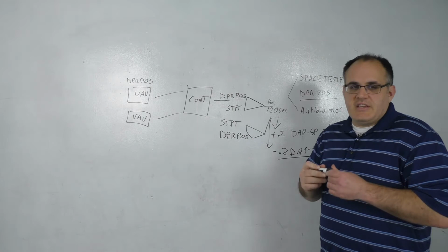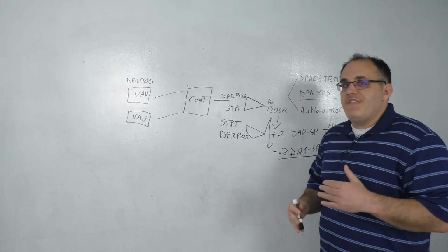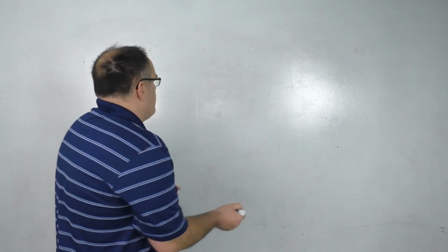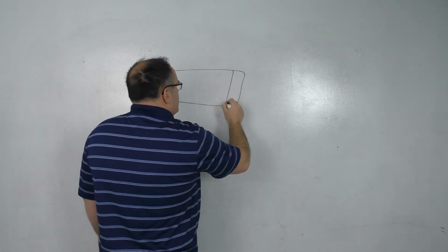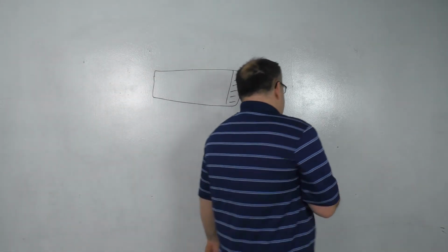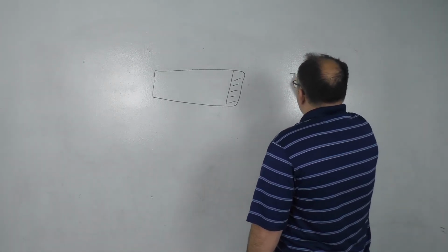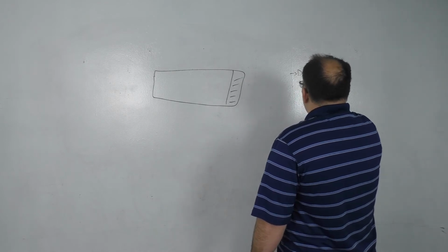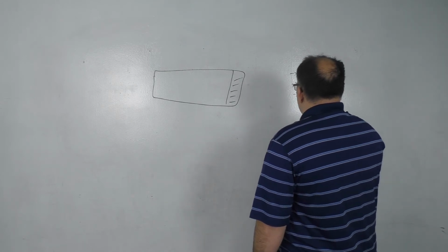Okay, so let's clear this off, and then we're going to go through economizer operation, which is everyone's kind of favorite area. So economizer operation, what is an economizer? Well, an economizer, quite simply, is a part of a rooftop unit or an outdoor air unit that opens up to allow outdoor air in. And there's really 3 ways we can optimize our economizer. We can optimize our economizer to control DAT, we can optimize it to control MAT, or we can optimize it to control CO2.